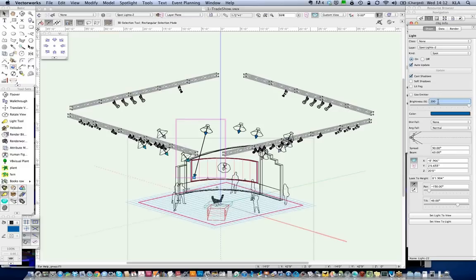I don't think that's great if I'm working on a light plot and I want to render a cue the way that it's really going to look based on the light that's going to be on stage or in an exhibit environment. On the other hand, when I'm roughing things out and I need to figure out how many foot candles or lumens I need, I can go beyond what seems logical or intuitive. Similarly, and I'm not really going to get into making textures today, but a lot of times when I make a bump map for a texture, or if I'm using a glow texture, I will set the brightness of that texture sometimes well beyond 100%. Sometimes a bump map I like at 1,000% or more.